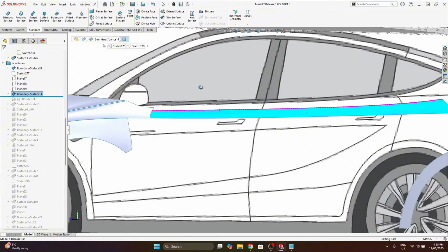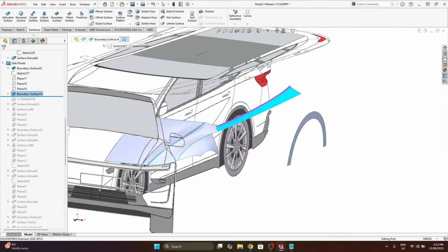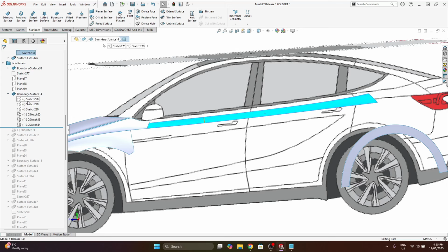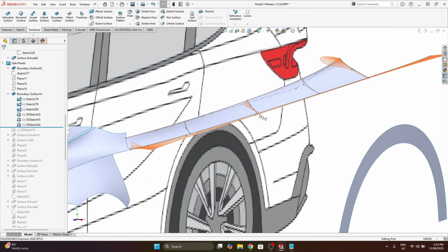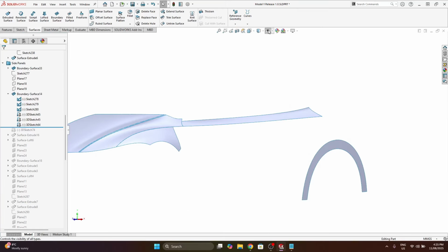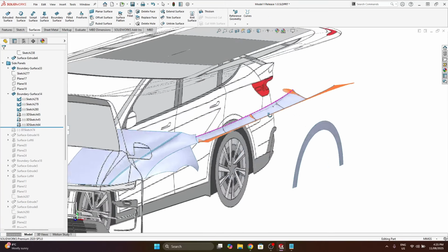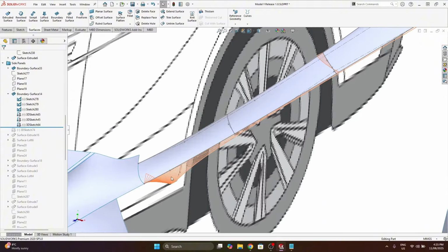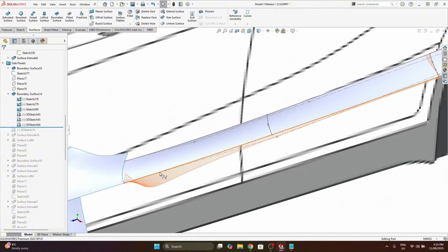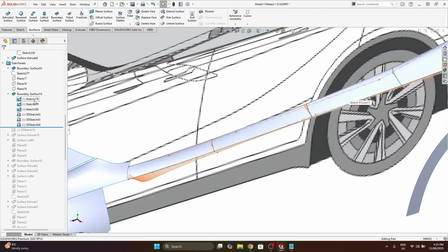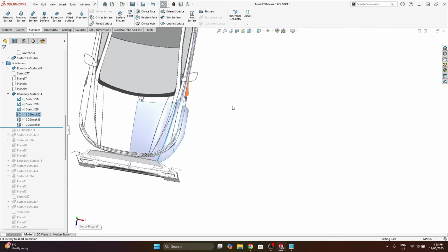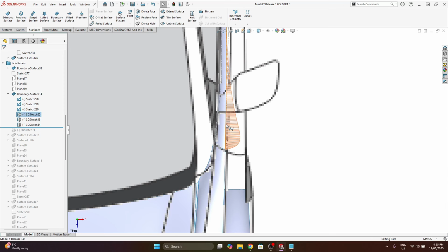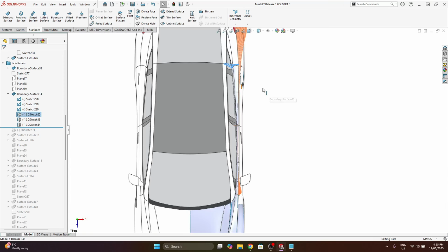Here I'm building up this long sweeping surface of the top of the side body. Again, I have most of these sketches hidden, but I can right click and show them. I can also hit this hide all types to quickly toggle that on and off. Generally I'm using curvature combs on these sketches, and sometimes I'm using 3D sketches, for example for this edge, which is a 3D curve in 3D space.